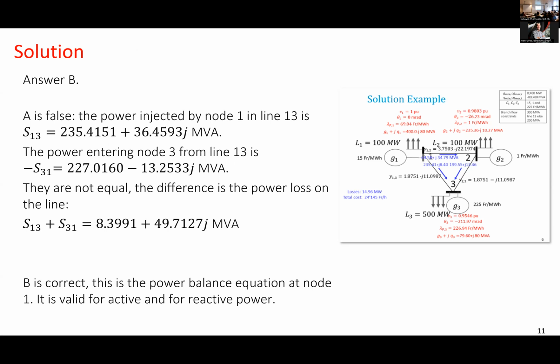The reactive power loss does not mean anything from a monetary viewpoint. It's just because the reactive power is no transfer of energy. So this is not important from a monetary viewpoint. It may have some importance because reactive power transportation requires a current, and a higher current will generate more losses due to the active power loss here. So we see this power loss, and that's, of course, what the grid means. So good grids have losses that are a few percent. So a few percent is both small and large.